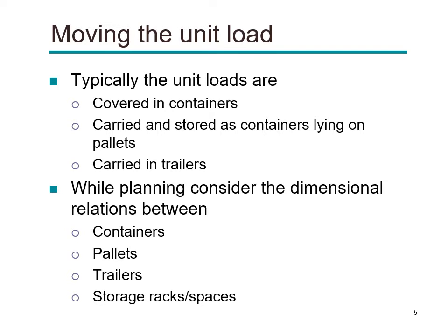Typically, these unit loads are covered in containers and carried and stored as containers lying on these pallets and carried in trailers. These are typical movement and storage of the items. When you are designing this material handling system and unit loads, you need to consider the dimensional relations between the containers, pallets, trailers, storage racks, and spaces. So usually there are some standard sizes for these.